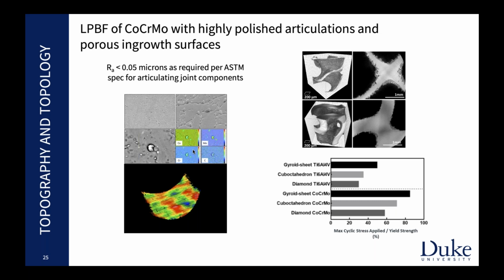We think some of that's just the sensitivity of the titanium to little small amounts of oxygen. But we can get really strong fatigue properties of the cobalt chrome, in some cases normalized compared to its strength a couple times higher than titanium. And so where titanium takes a pretty big hit in fatigue properties, cobalt chrome is actually pretty close to the raw material. In fact, it's in the 50 to 80% range of the yield strength, which is really high for fatigue strength.